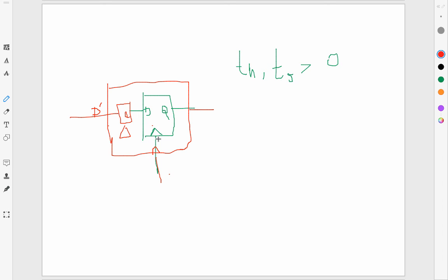Because what you normally get as a unit is not really that bare minimum flip-flop, but that flip-flop surrounded by other stuff. So the concepts of hold time and setup time are things we can talk about for any sequential logic. I give you a sequential logic and you can define for me, for a given input relative to the clock, when it can change. So they are about sequential systems in general, not just flip-flops, because they are telling me when I am at liberty to change the inputs.